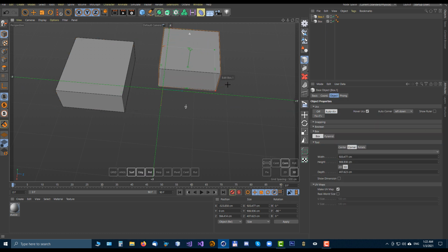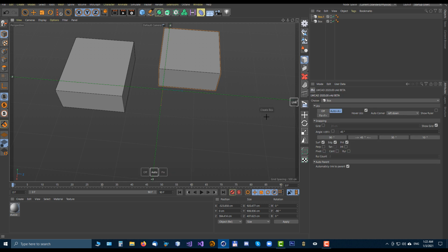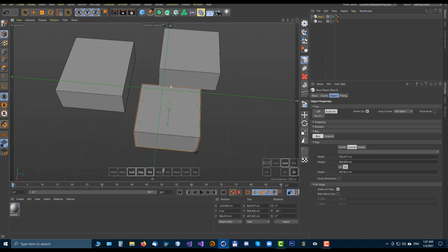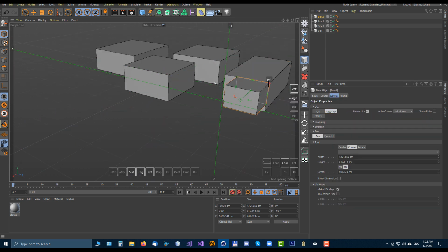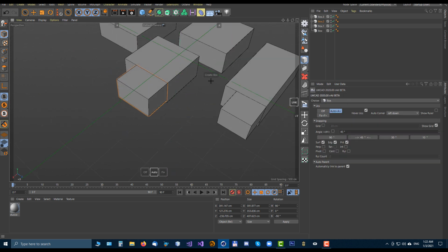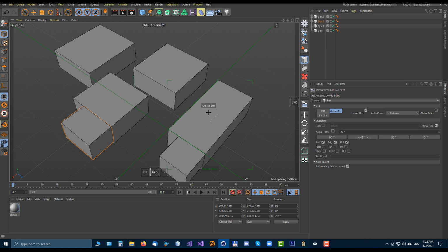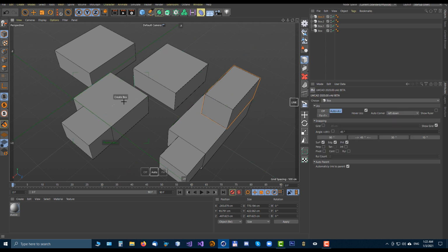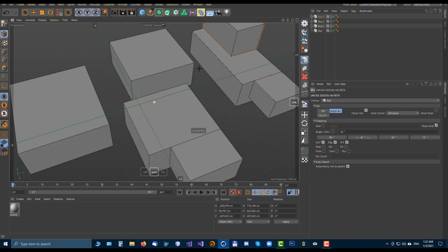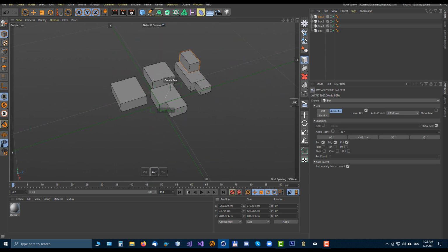Again, the right mouse button will end this object, and with the left mouse button you can start another edit phase of the next object. This way you can easily create a lot of objects and place them immediately on the position you need. So together with snapping and UCS, automatic UCS, it is a very powerful system.